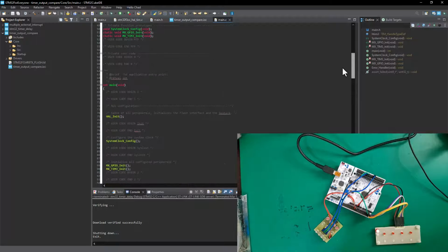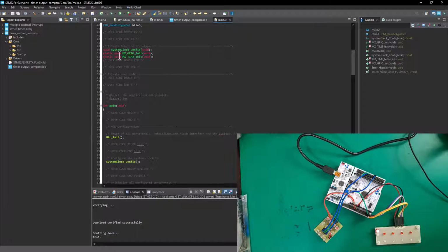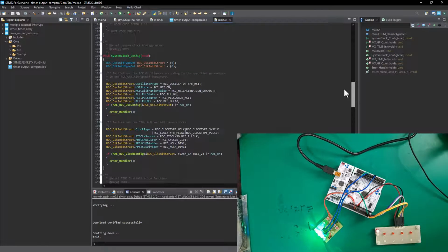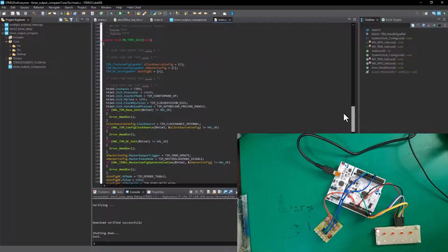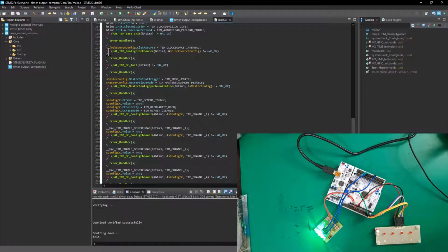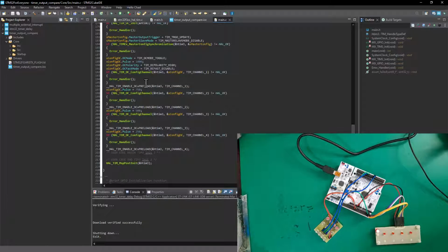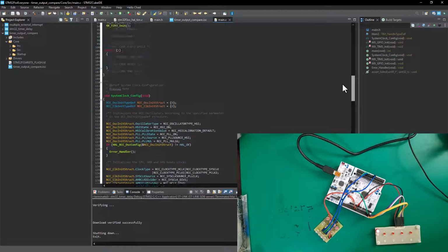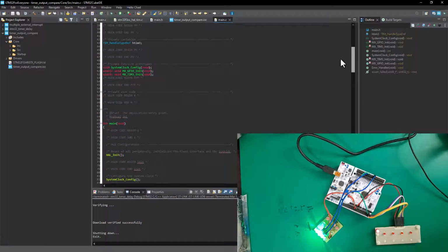We can see that we've got the usual initialization and the timer variable for timer 1. Okay, that's the only one. We've got the system clock is set up and our timer 3 initialization. Now, this is where we've got all the if statements here to basically turn each one of the channels on at a specific timer overflow. You can see the 1000, that's 1 second, 750 milliseconds, 500, and so on and so forth. Great.